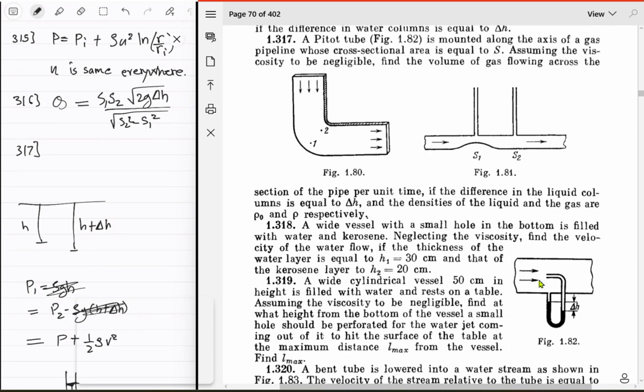Hmm. Come on, think about it. Maybe you can assume that, no, you can't just go on assumptions. You know for sure that the speed over here is just zero throughout, right? Then at that point, the streamlines can't be going in and out. That doesn't make any sense because of symmetry, right? There's a cylindrical symmetry to this thing, which means, okay, that's weird. So till that tip, even at the tip, it's the same pressure and the flow speed is just zero.